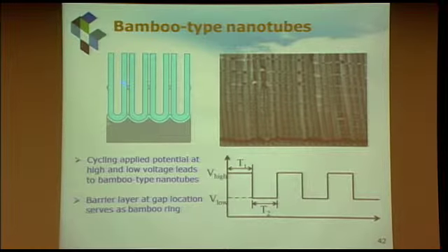We call them bamboo-like because they have these joints at different locations. You remember the tubes actually were smooth during this merging, splitting, merging process. But we can change our anodization voltage during this process, like high voltage to anodize it, and then lower the voltage suddenly so that the walls will grow like this, and then increase back, go back to business like nothing ever happened.